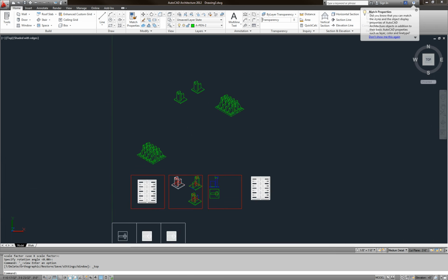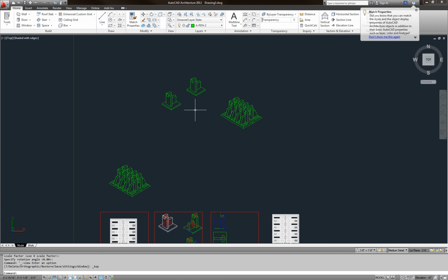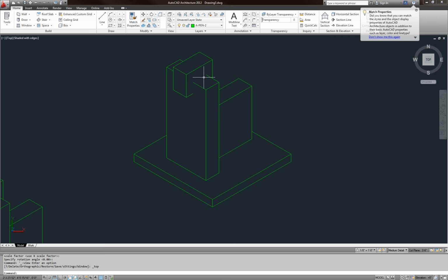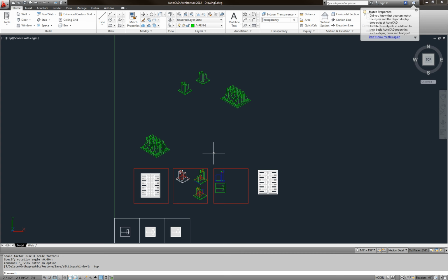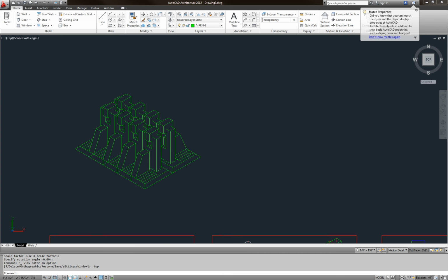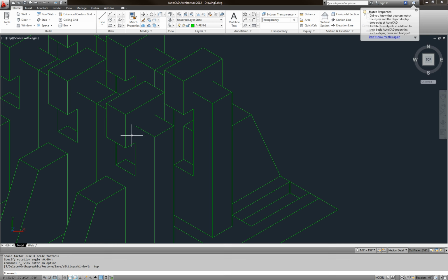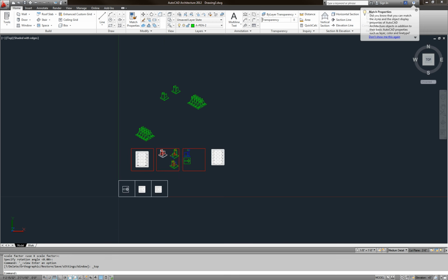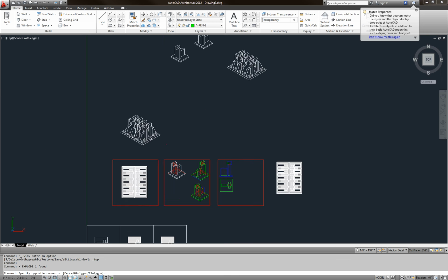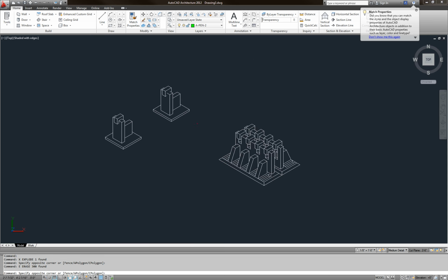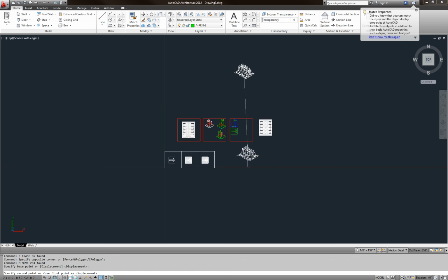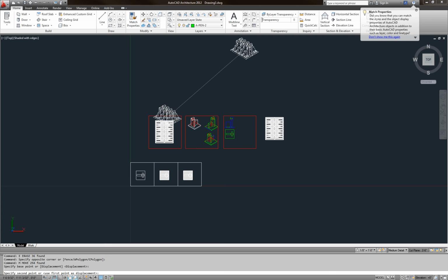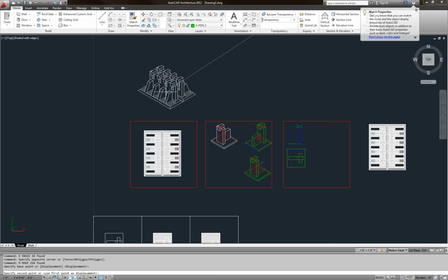See, the problem is that when you do isometric view, guys, since there's no hidden line, you'll see the default. Whatever 3D you have, it's going to make a 3D object for it. So you can see that this is wrong. See, it's missing these lines. So I'm going to select this, explode this, and delete this guy here. Delete all of this. I'm going to take this, enter, move it, and I'm going to move this about here.